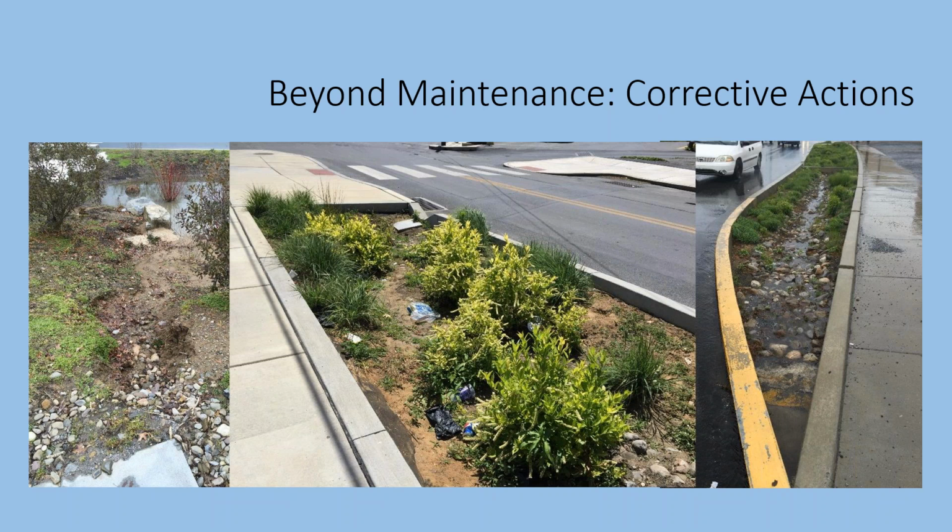So the photos that you see here are 3 rain gardens that were installed as part of the pilot project process that I mentioned earlier. And you can see in all of these photos that there is some very severe settlement and erosion. There's also ponding water that is not evenly distributed. And in the far right, you can see that the low flow channel is doing an amazing job at being a low flow channel, but those plants on the upper slopes are a little bit too high to really serve much of an effect in terms of what the city was expecting. Next slide.